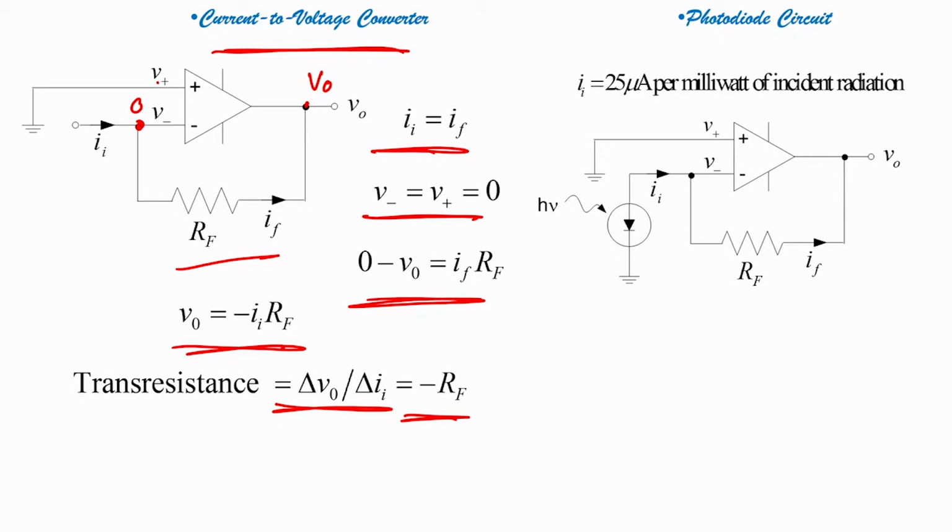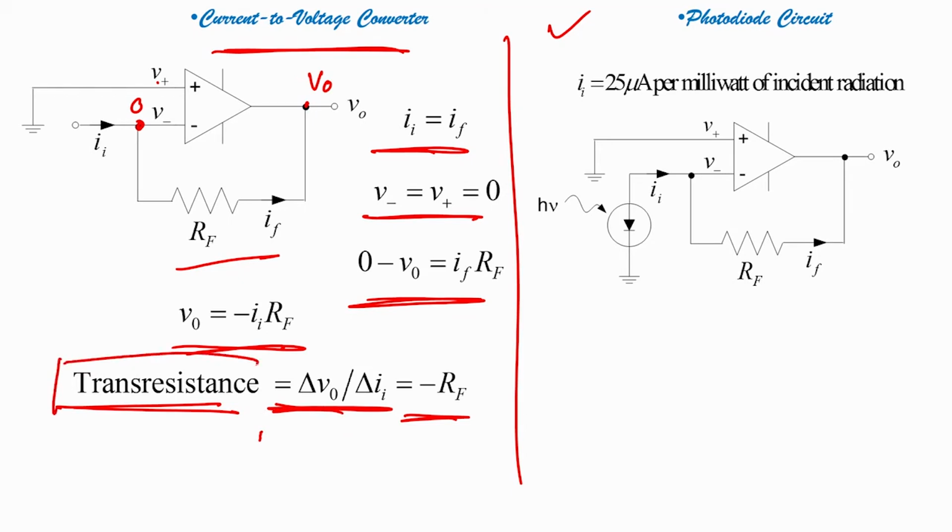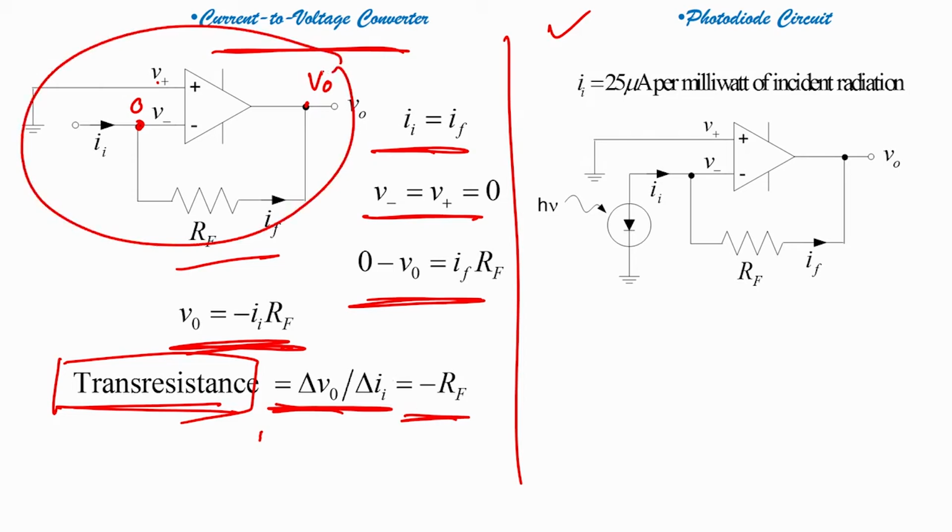Okay. Now, let us see this particular circuit. I am not going to teach you what trans-conductance and trans-resistance are; you have to understand how trans-resistance is defined and how we have written delta V0 by delta I1. So, understand what trans-resistance is, try to learn by yourself as well. Now, V0 equals minus I1 RF, correct. So, this is the value of output voltage for the given circuit.